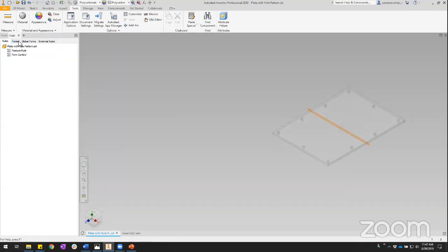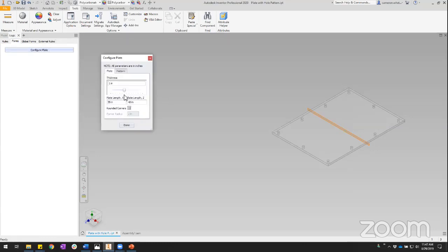Now, let's launch our form. And you can see if I am below 1 inch, it's fine. I have the option to add rounded corners. But if I go above 1 inch, now this option is disabled. So that's working the way I want. But I want the actual corner to not just be an option to select, but to actually not be chosen, selected. And I want this corner radius to go away.